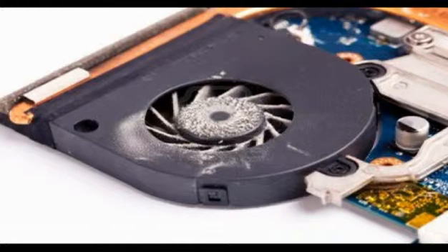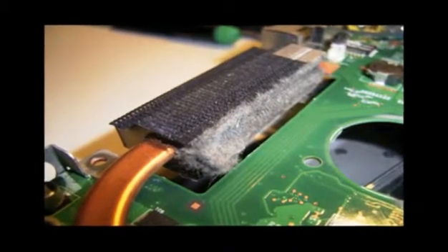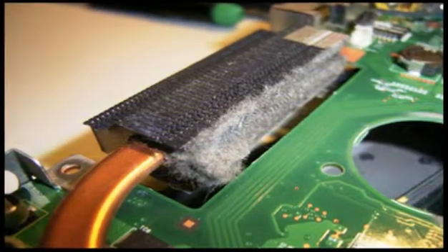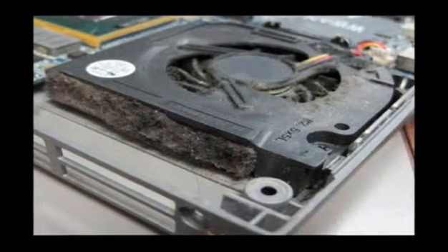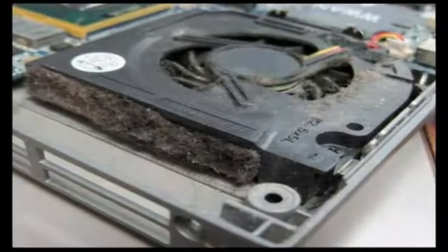One of the components that drains battery power is the fan. So it's always advisable to clean your fan, I mean your CPU fan, especially the air ducts where the hot air from within your motherboard is blown away by the CPU fan out of the system board. If dust is blocking the flow of air, the tendency is that your fan will keep on spinning, thus consuming your battery power. So the more you can hear your fan spin, the more it consumes battery juice, and thus drains your battery power.